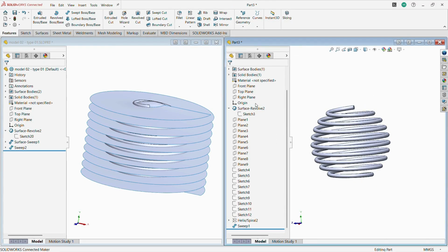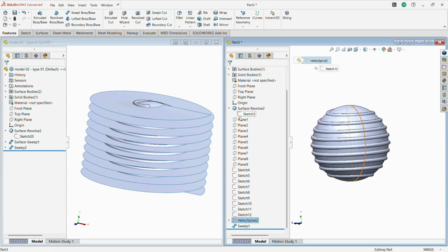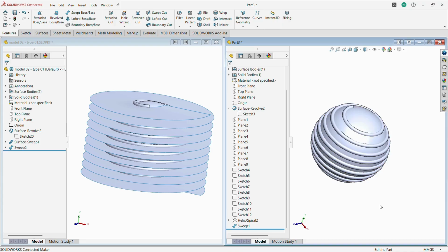But if you take a look at this right side, it is a precise one, but takes much time compared to our previous one. You can control the pitch distance. You can control the arc angle, okay, by initiating the variable pitch diameter, revolution type, pitch distance one by one, but it takes time. That is the difference in creating any kind of solid body.